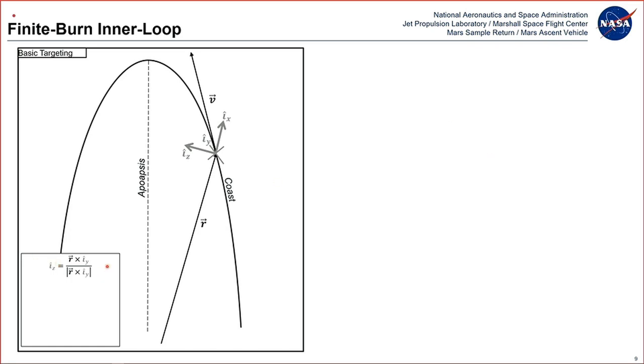First thing we do is we define what's called a target frame, or a guidance target frame, which essentially represents your radial, downrange, and the anti-parallel to your orbit normal. For those of you that are familiar with PEG and the heritage PEG, and now for SLS, PEG's derivation, they actually use a very similar guidance target frame representation. It's a good way to kind of organize your equations in a frame that makes sense with no requirement to be inertially fixed. So yeah, it's really simple at this point. We've got a position magnitude.